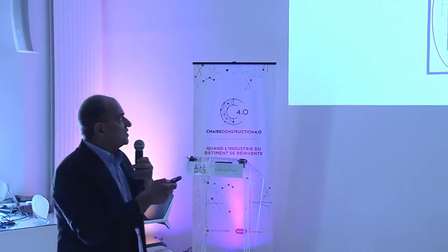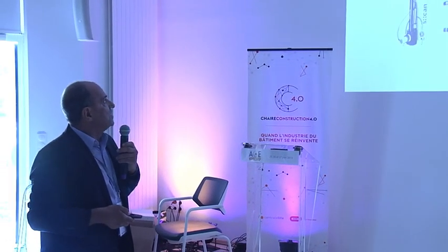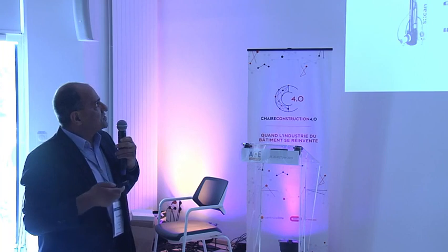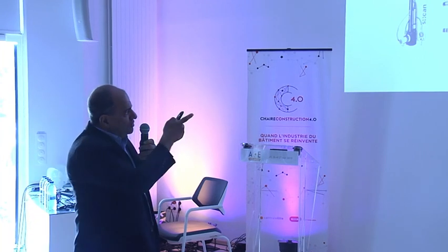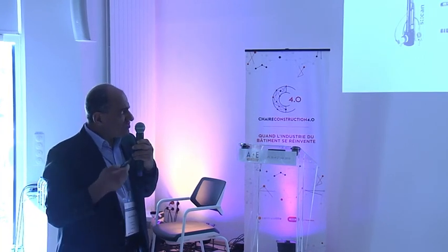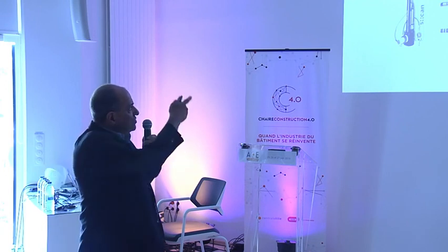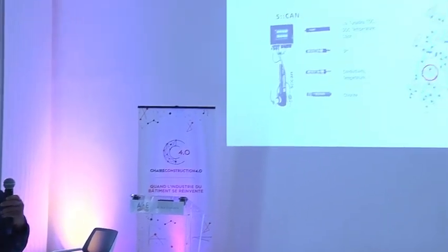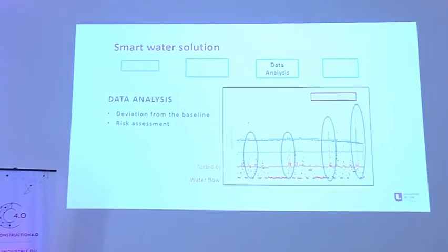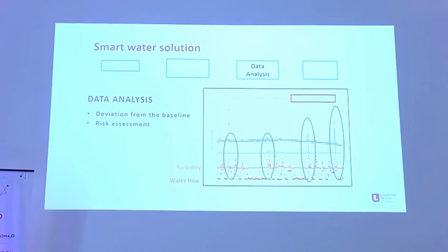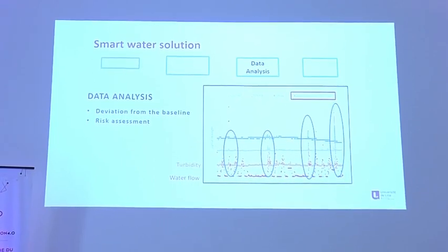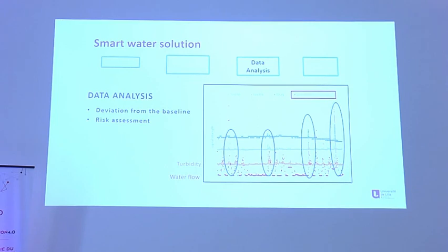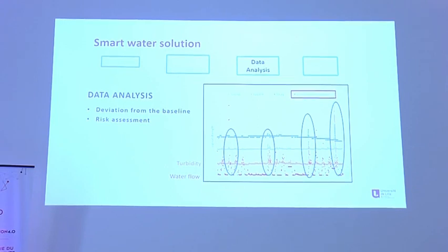Something which is very important about this: here were all the leaks which we resolved. The second thing, which concerns the water contamination, we have also used some advanced devices to measure all of these parameters: pH, UV, conductivity, chlorine, and so on. And we can get the data almost every 2 minutes. You can see here also some of these results. When it's horizontal, it means that it's normal, and sometimes we have this change in the water quality. It means that we have something.